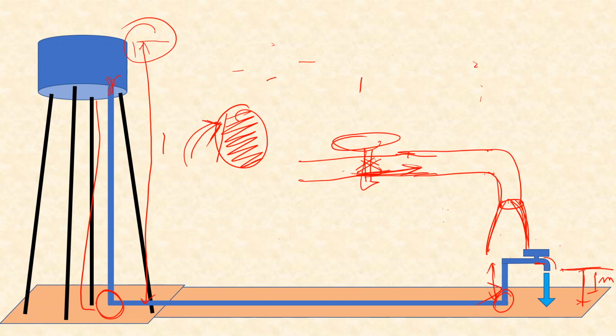That's because as soon as you let water flow through only a small cross section through this valve, that means over this part there is no flow, only through this portion flow is taking place. In that case, the flow will take place like this and there will be some kind of spiraling flow, and the flow will exit this outlet only by the side or by making 2 or 3